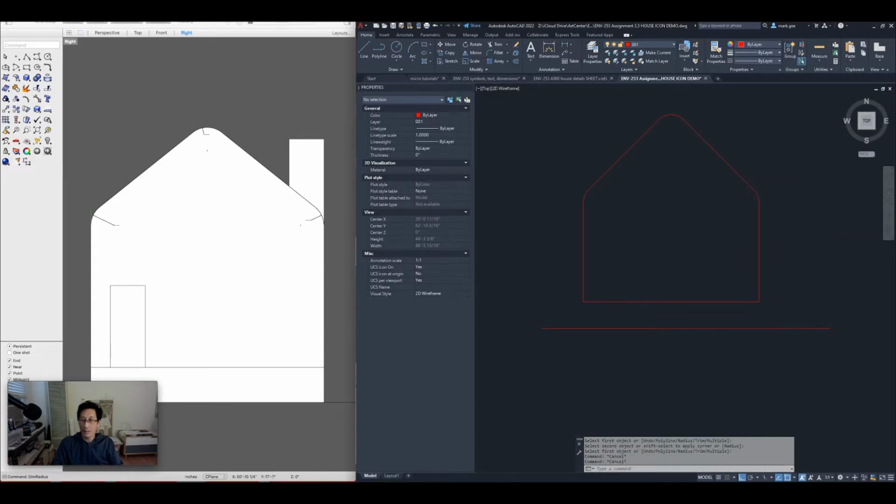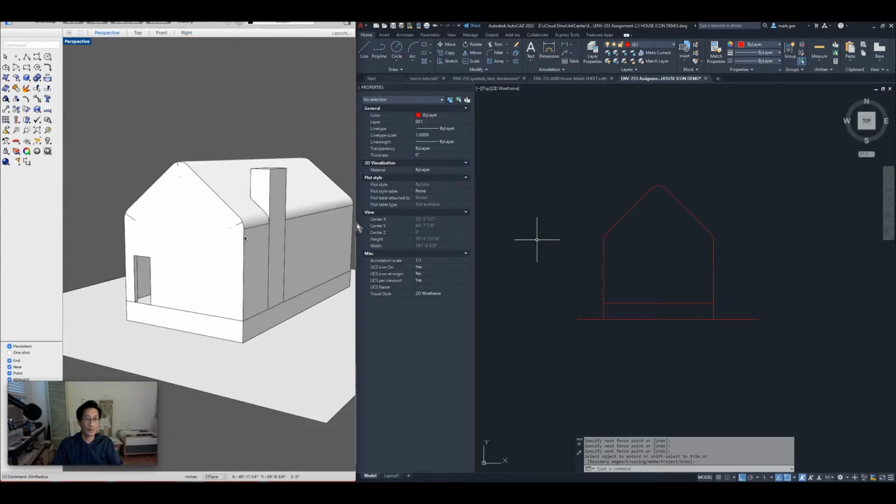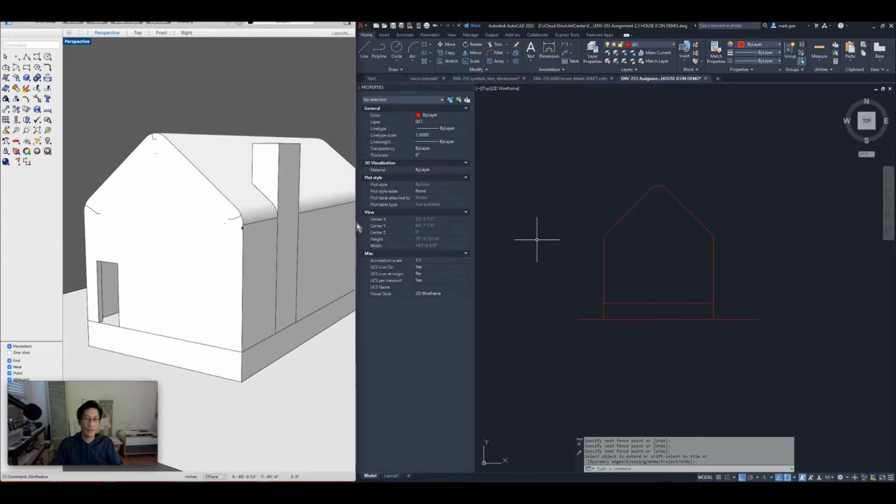Okay. Now let's make sure that all of our heights and other things are connected. I actually want these lines to connect down to the ground. So I'll use the extend command EX and just draw a line through those there. Okay. And what we can do here also is go back to Rhino and double check, going to perspective and zooming out a little bit, how high this break point here needs to be above either the ground or that first level. Let's do all the way to the ground.